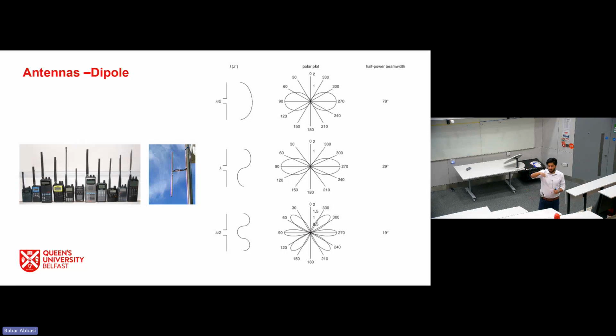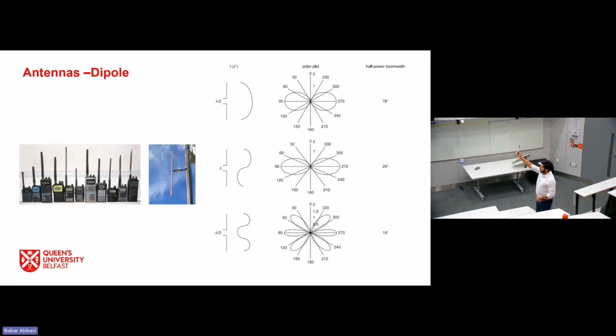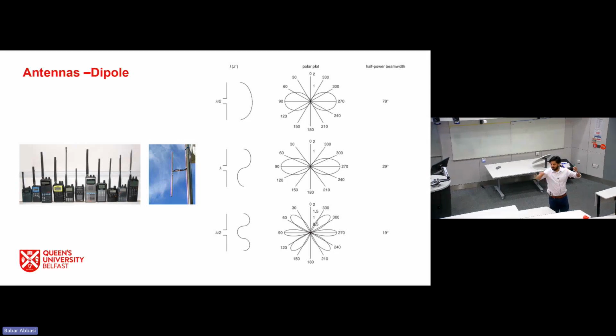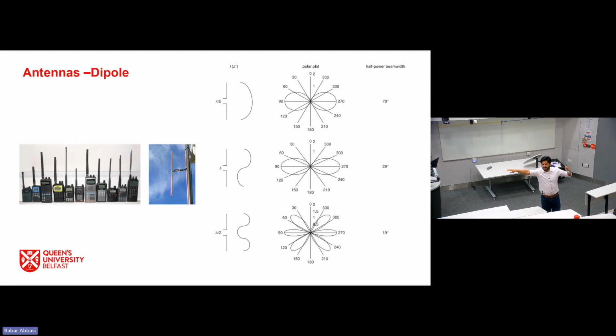What it means is it has a contour, and this contour represents a value in the direction we are interested in. So imagine my dipole antenna is sitting like this. Then this contour is saying a high value in this direction. It means there is more directivity in this direction, but this contour is getting smaller and smaller as I move from theta 90 towards 0.